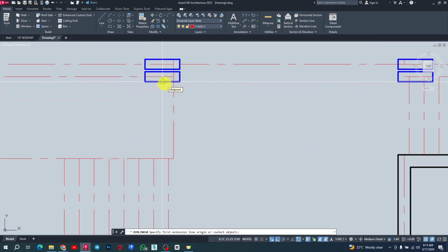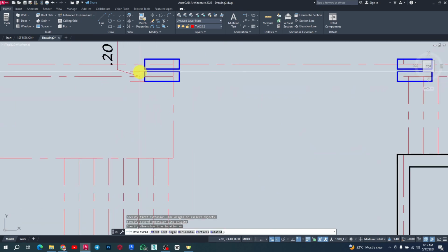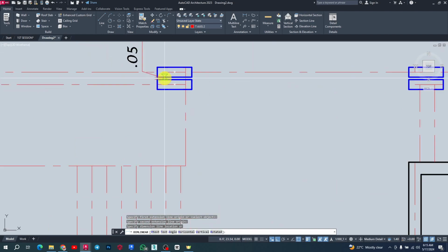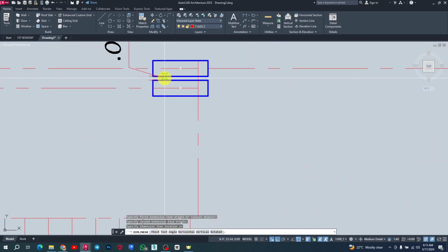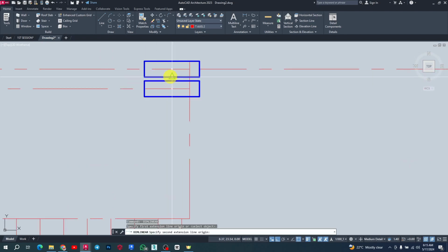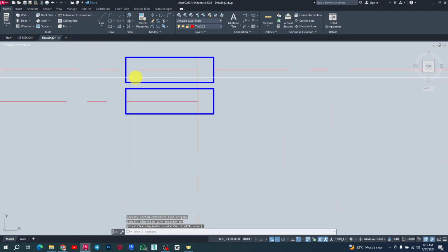Okay, so that 5 millimeter comes only between the slab. I'm going to have a beam that runs on this one, with a width of 20, that is 200 mm. So I have 5 millimeter again here, which is the thickness of the polystyrene. Then we will also have another one of 0.03. I'm going to be using 0.05 in my case, so I'm going to leave this space to be 0.05 so that the polystyrene will fit here.